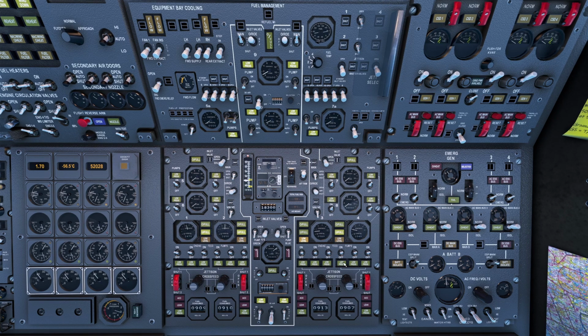As the situation, even if we are in descent, is getting a bit dire on the right side, I'm not caring that much about the center of gravity, so I'm gonna stop the transfer to the front and I'm gonna pump fuel on the right side. It's gonna also affect the CG a little bit, but less, because these tanks are, as mentioned, really in front of the aircraft.